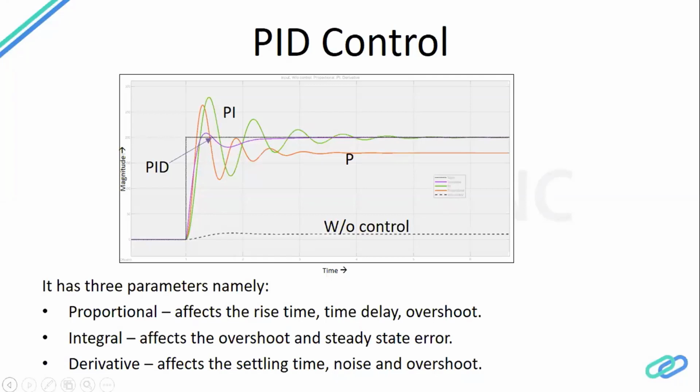Now, if you are not familiar with PID control, then I would like to discuss briefly about it. The proportional term is like a constant which multiplies with your error, and it amplifies the signal basically. Suppose you are getting this dotted response, which is without control. What will your proportional term do? It will calculate the error, send it to your controller, and then multiply or penalize it, which is like telling your system that there should be more input to get the response we want with respect to our requirement. Thus proportional control will act, and you will have the response which is in red.